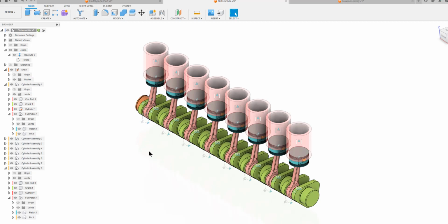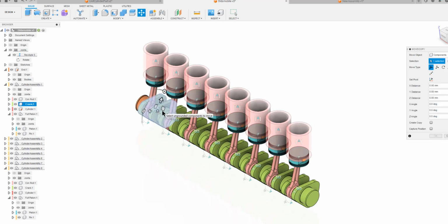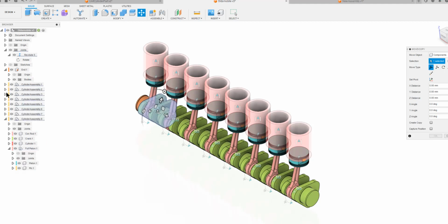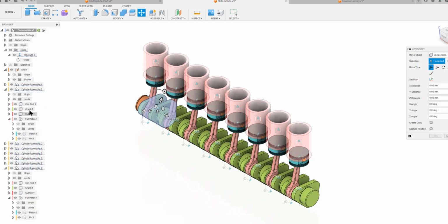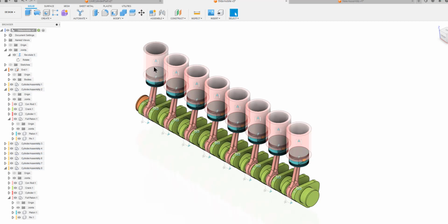So the next thing for us to do is to now begin to apply our angular orientations. To apply the angular orientation, we pick one cylinder at this point and take a rotation. Is this cylinder, is this crank? So if we choose that crank in the second assembly, no, not in the second assembly, so let us go to the second assembly crank. So we take this crank and then we are going to give it a rotation through an axis, the axis of the rotation.